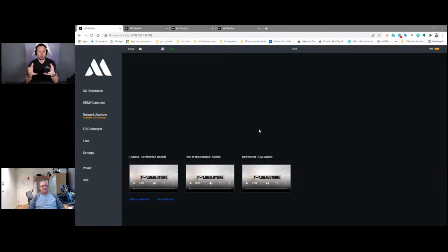So we'll see here when we run the DC resistance tests, these take seconds. Sometimes it'll take longer to plug the cables into the unit and get it configured physically than it does to actually run the test. So when I show up on site to help a dealer with these troubleshooting calls, we'll usually know within minutes if the cable has a problem, or if the cable's okay, or maybe it's another cable, or maybe it's a transmitter or receiver. Whatever the case is, we know very quickly, and we don't have to just randomly start swapping hardware to hopefully fix the picture. This is a very simple test, doesn't take much time, very helpful for the guys out there in the field.